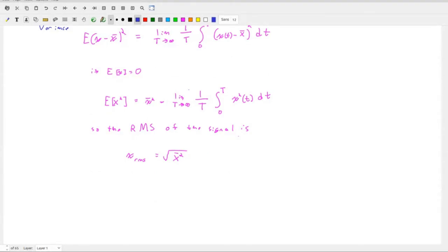So that gets us to RMS. Now, considering a non-stationary signal, right? So what's the stationary signal? No. So a stationary signal is a signal where the statistical properties of the signal remain unchanged, right? So it would be random noise, but your mean's the same, your variance is the same, your RMS is the same, right? A non-stationary signal is where your statistical properties change through time, right?